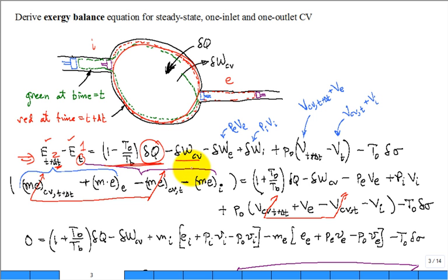We have a control volume, a little transfer of work out of that control volume. You have a little work associated with pushing the fluid in and out. Think about a little piston, an imaginary piston, pushing that fluid in, and a little piston being pushed back as some fluid flows out. Those are those two boundary work terms. You also want to subtract off, or take into account, the pushing back of the atmosphere at constant pressure P naught, which is not needed.